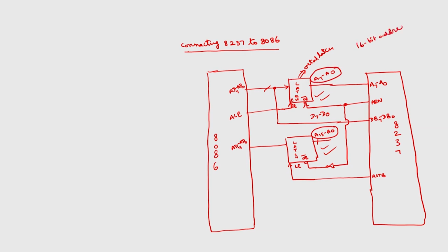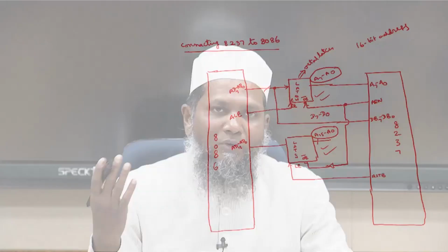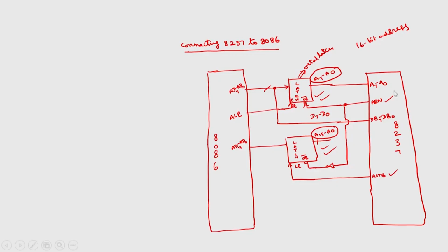Because the memory address is 16-bit, the starting address of the memory MAR is 16-bit. So, we have to place a 16-bit address onto this bus. So, this is how we can use this address strobe signal and AEN signal to demultiplex address and data buses.